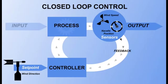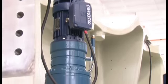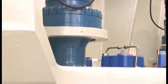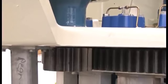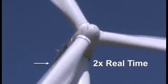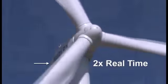When the wind direction changes, there is a difference between the set point and the nacelle position, and an error signal is produced. The error signal is used by the controller to produce a correction signal that will set actuators in motion to move the nacelle to the set point. Actuators are devices such as electric motors or hydraulic cylinders that create motion and can be controlled with an electrical signal. The controller turns them on in order to bring the system back to the set point, and then it shuts them off until the next error occurs.